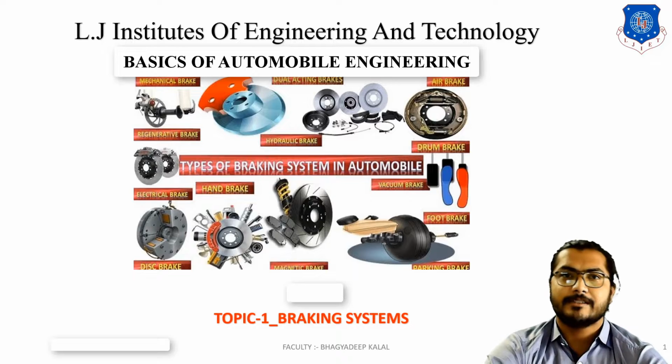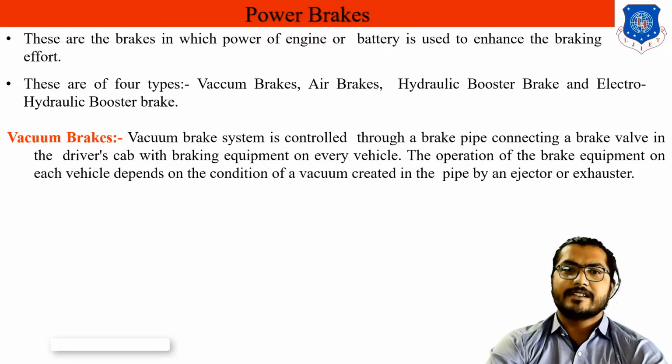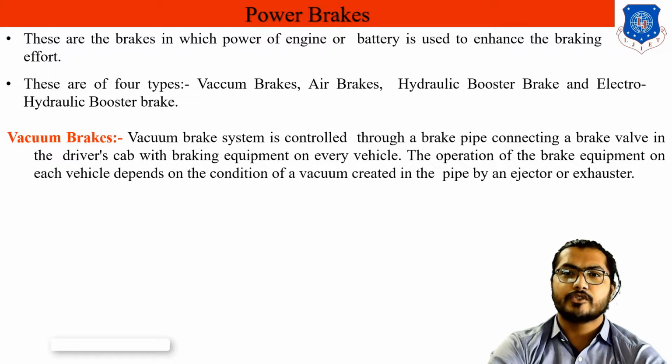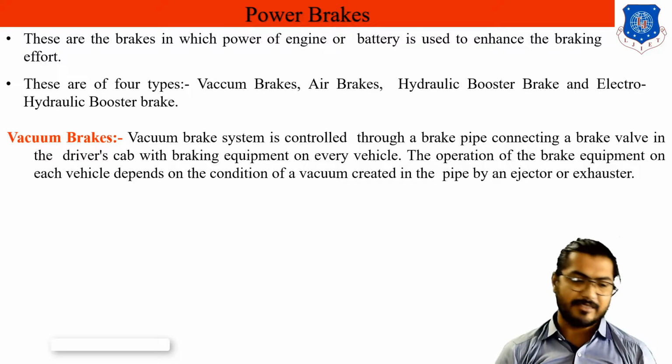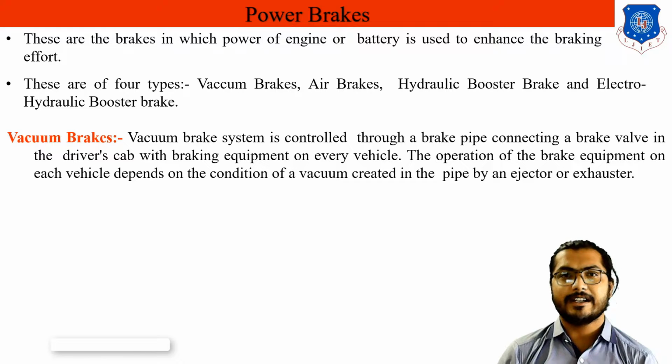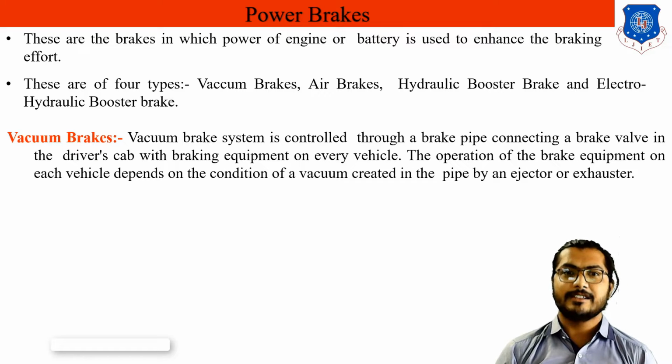So let's discuss the next, power assisted braking system. These are the brakes in which power from the engine or battery is used to enhance the braking effort. That means the power braking system increases the power supplied to reduce the braking effort for drivers. That's why we take some power from the engine, or from the battery as an external source, to reduce the driver's effort or human effort, so that the brake can be applied easily on the pedal. So that is the power braking system.